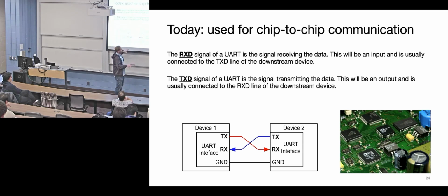The way we use these on embedded systems now is usually two devices talking directly to each other. There's not really functionality any longer for multiple devices; you'd have to have muxes and all those sort of things. So it's good for two devices talking to each other. You'll often see a microcontroller talking through a UART to USB converter, and then you can talk to your computer. Wireless modules like XBee are another way, where there's only really one computer or one wireless module at a time on a particular microcontroller.